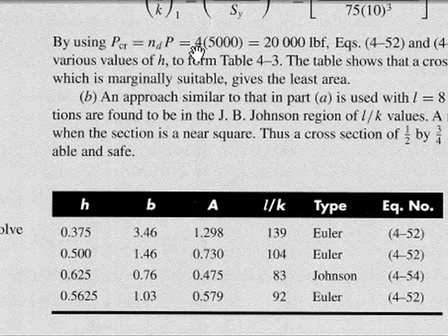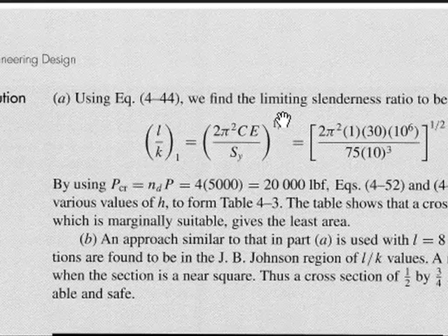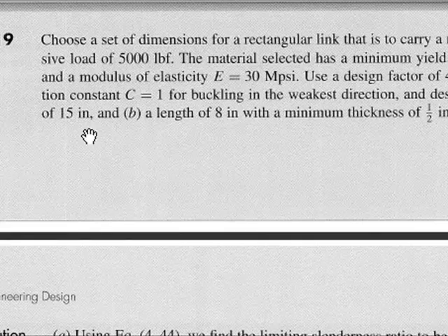It may only be about a 3.95, but I think that's a reasonable exchange. We'll go with a slightly smaller standard size, and we'll only have a factor of safety of 3.95 instead of 4, but I think that's probably fine. This is the work that was done using a 15-inch length, as the problem statement said.